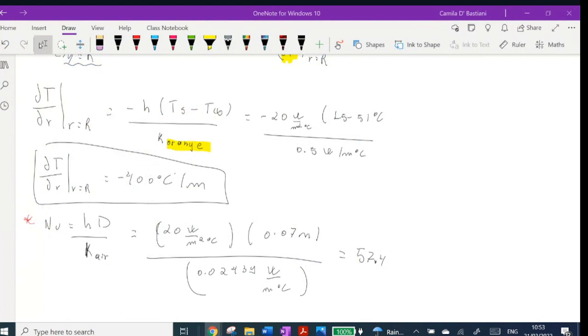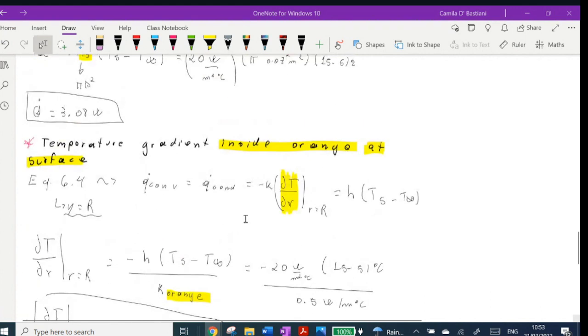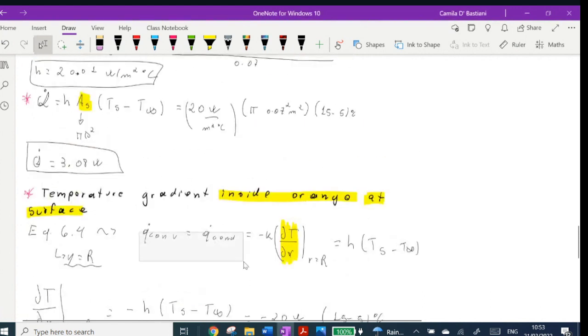For part B, you assume the convection heat transfer rate is equal to the conduction heat transfer rate at the start. Yes, Connor. So we assume that my convection heat transfer is equal to my conduction. It's not exactly to do with the start, it's to do with the boundary layer. So it's more with the fact that we are assuming a no-slip condition.